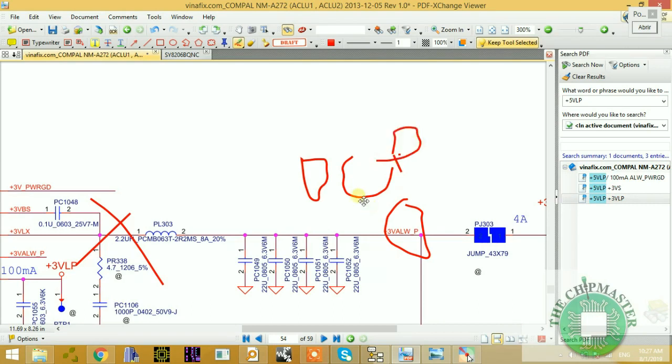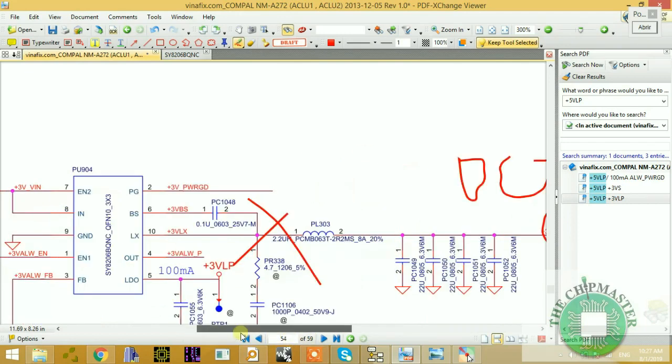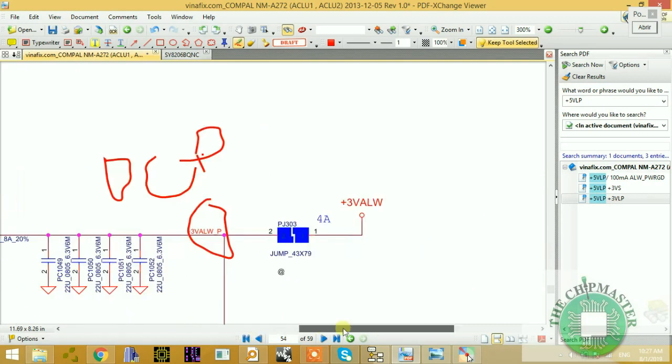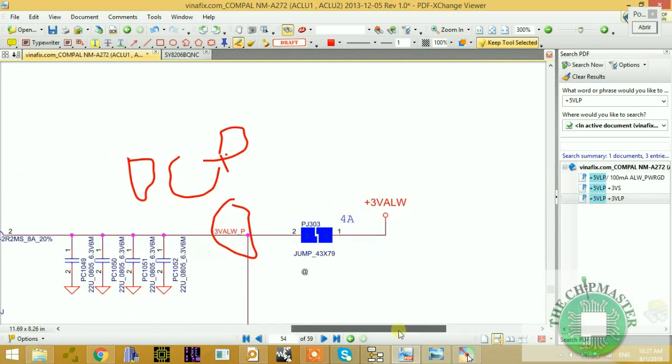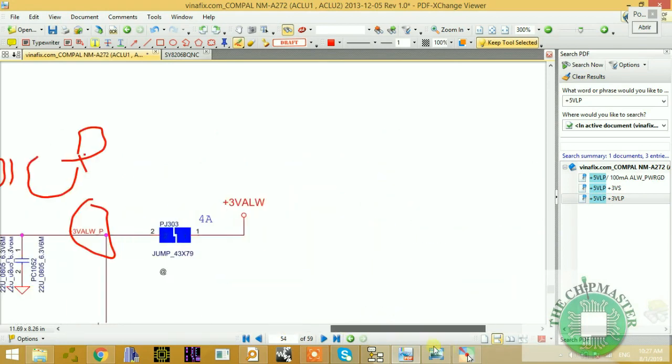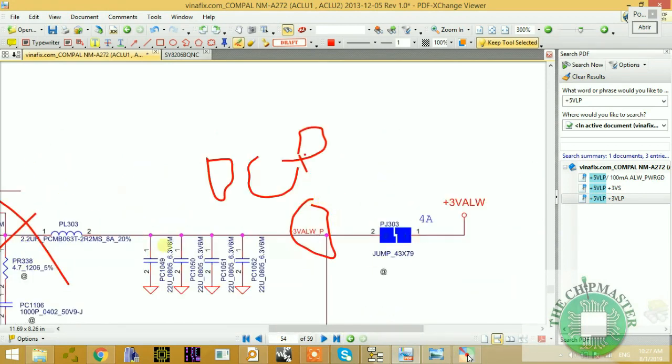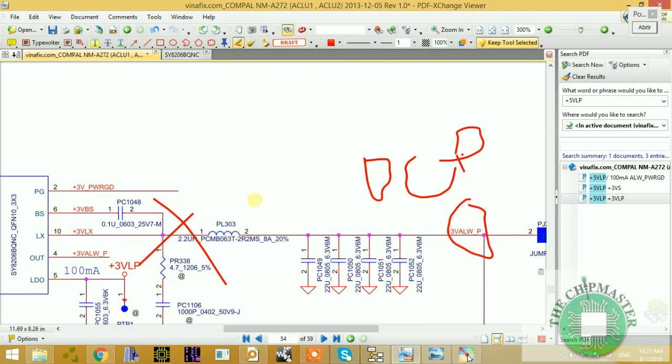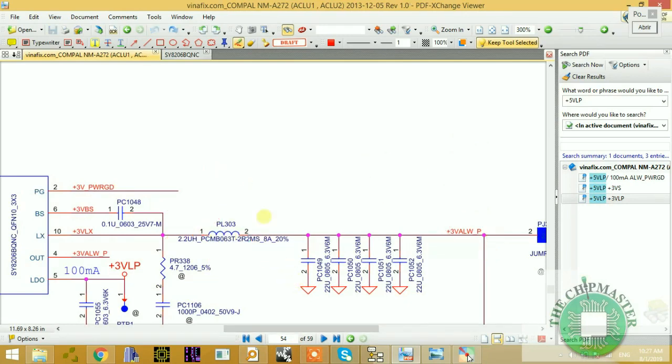I'm going to show you the data sheet in the next segment, and some of the functions of these pins, for you to understand clearly, right? So if there's any overcurrent or any short circuit on this path, then it won't output any voltages, because you have an overcurrent protection. So there is a short on this coil, so it will cut off the output voltage, right? If you have an over voltage protect, if it's OVP, if there's an over voltage, right?